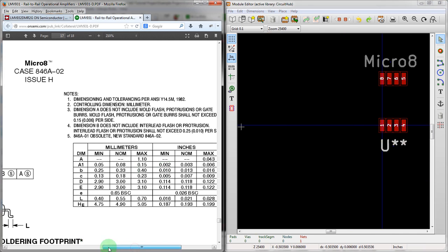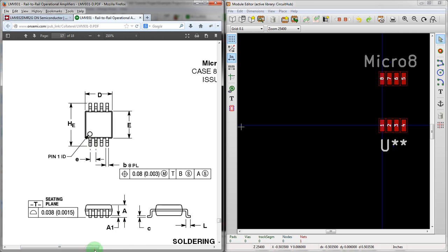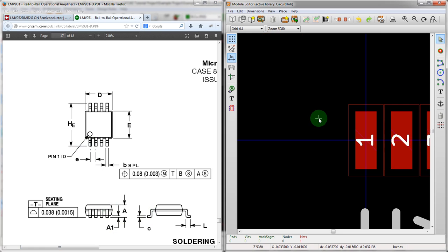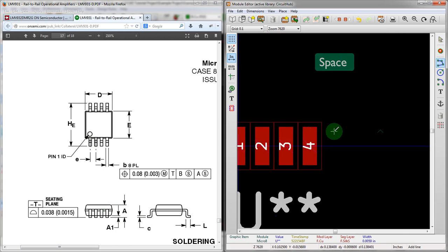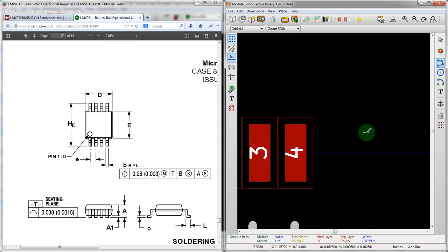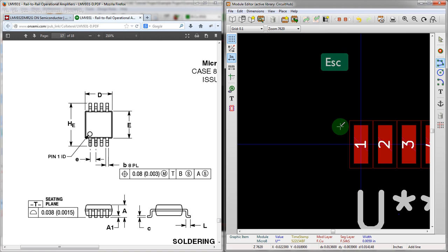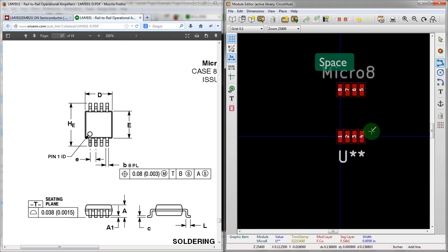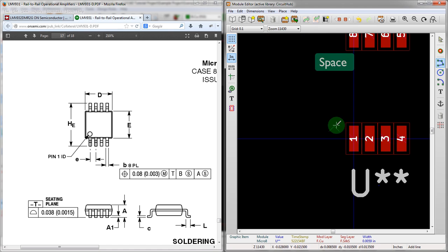When we look back over here at the footprint, we see the footprint is actually the entire amount that the pads want to contact. So usually there's a bit of overlap, as you see these legs curl down. So there will be a little bit of footprint in here. So let's kind of skew it inwards. Set that as our reference. Right about here. I set that too far. Let's just measure this to start with. So this to about here is right about it. So move it right a little closer.